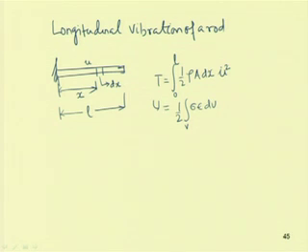So, the stress can be written. Already you know that stress, if it is subjected to a force F, can be written as force by area, or in terms of the strain you can write stress by strain equal to E. So, stress will be equal to E, that is Young's modulus, into the strain. One can write the strain equal to del u by del x. So, strain is del u by del x. So, stress equal to E into epsilon.